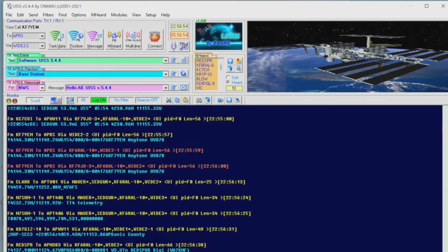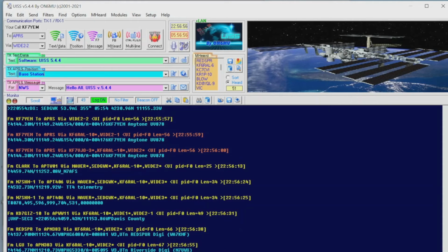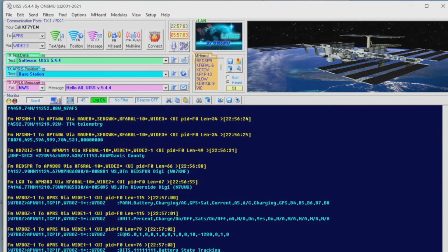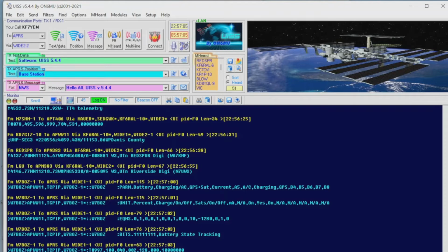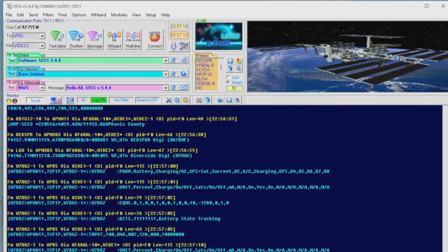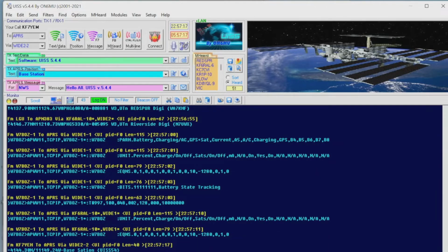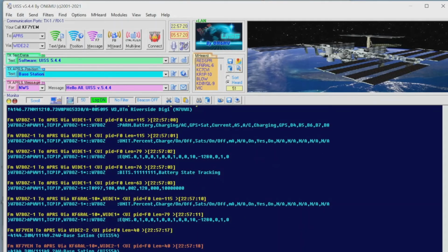One of the smart things when I'm doing these tests is I try to wait for it to be quiet here, because that tells me that any of the repeaters are actually ready to listen to a signal. So once it quiets down again, I'll go ahead and hit that button. And there we go. I got one back in on it, and it was digi-repeated at least once.